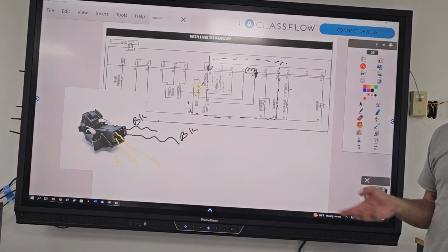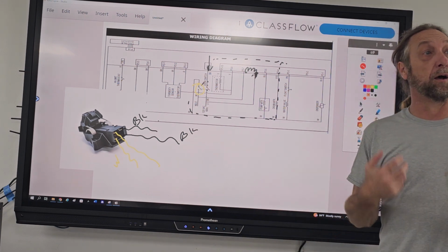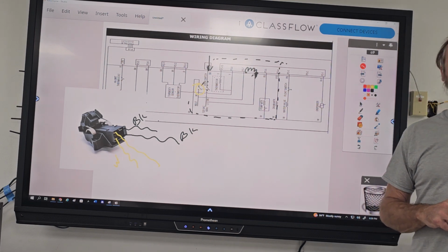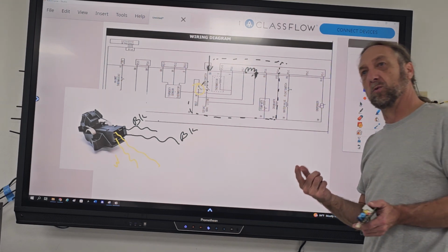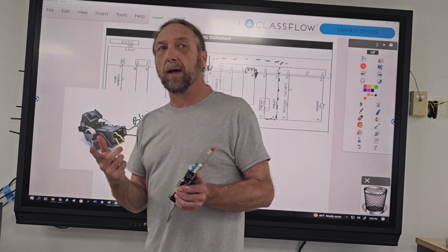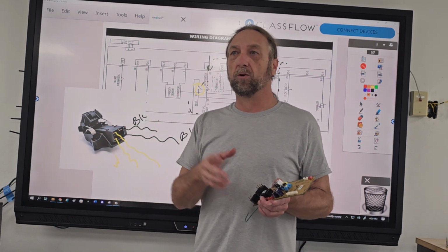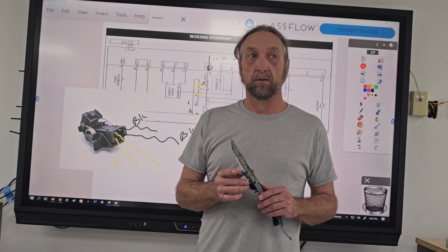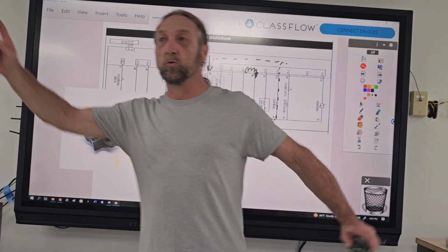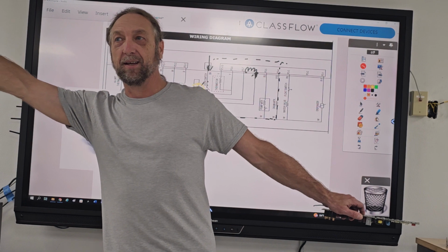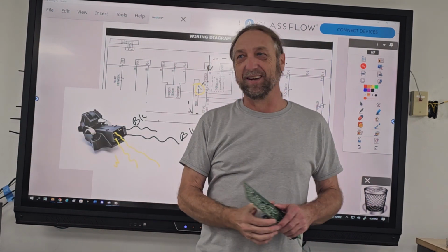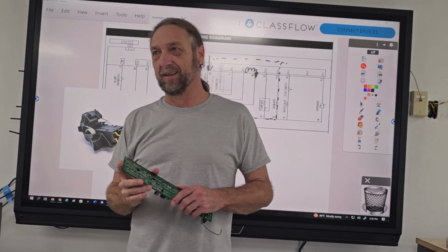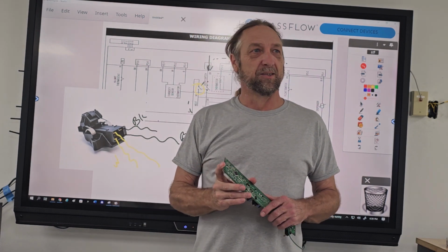Now, if both of those switches gave me a reading of 0 ohms, is that good or bad? That's good. What is a bad switch reading? OL. OL, which is another word that starts with I. What did Buzz Lightyear say? To infinity and beyond. Infinity. Infinite. That's right. Infinite. Okay?